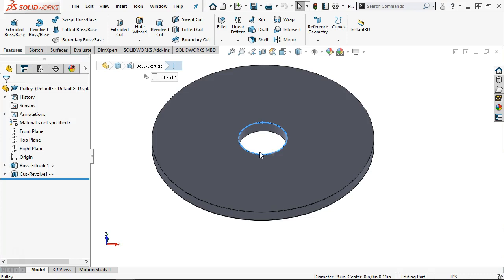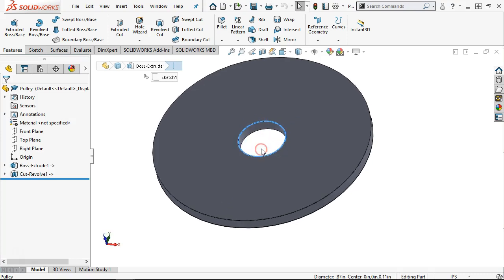And I think we calculated out at about a thou and 6/10, or maybe a thou and 8/10. All right, so I'm pretty comfortable with this number, and since I have the bearings and can put a micrometer on those, then I can get a reasonable number and know where I'm going to land on these. And like I said, I order 2, they show up on my doorstep, and I measure them, and we're not looking at a manufacturing range or a specification that's really going to use up that 0.6 of a thousandth tolerance in the bearing.